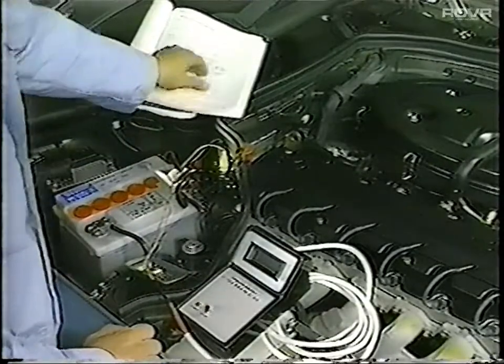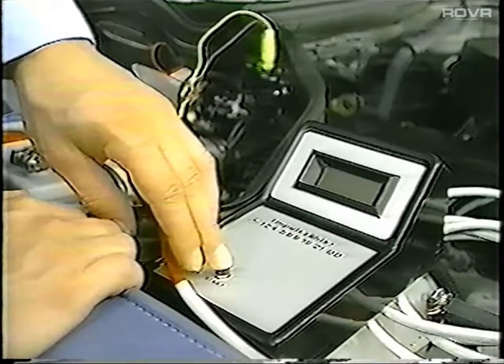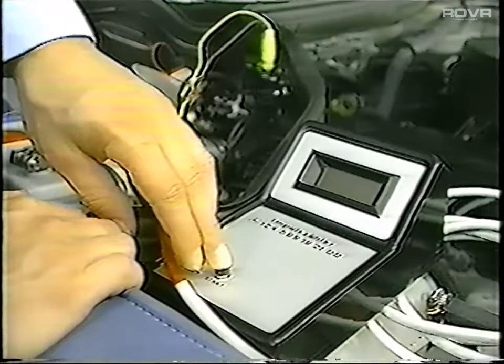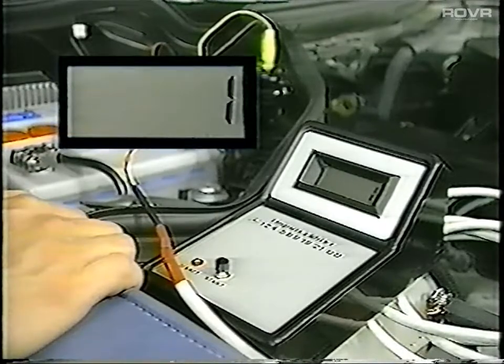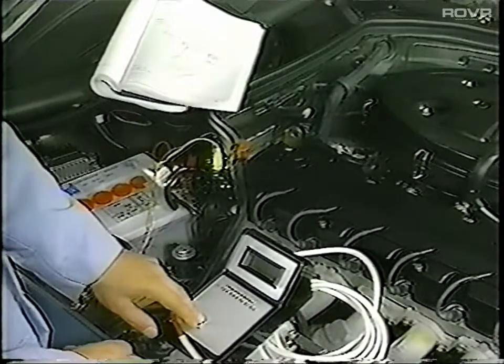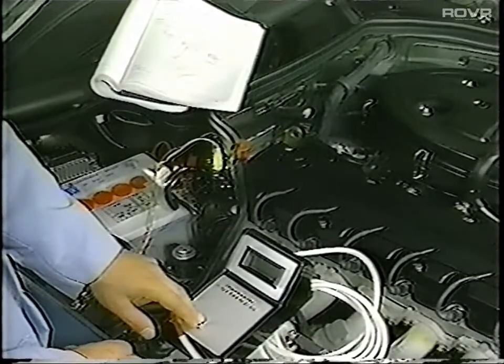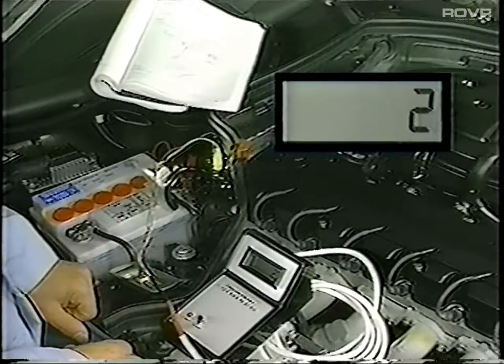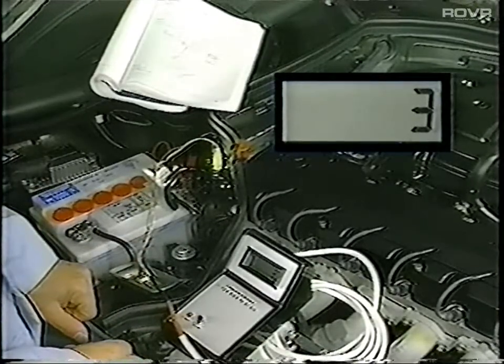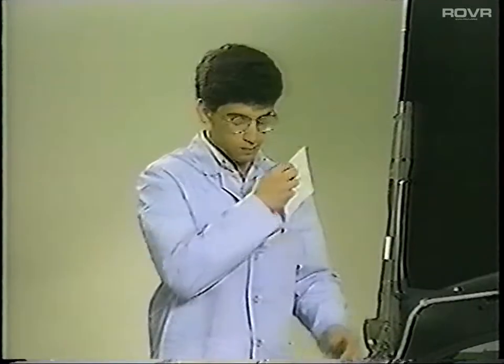Press the button for no less than 2 and no more than 4 seconds. If the number 1 appears and locks in, there are no faults in the system that are present at this time, or that can be detected by the diagnostic circuitry. If there is a fault in the system, the tester will continue to count. When the tester stops counting, record the number.